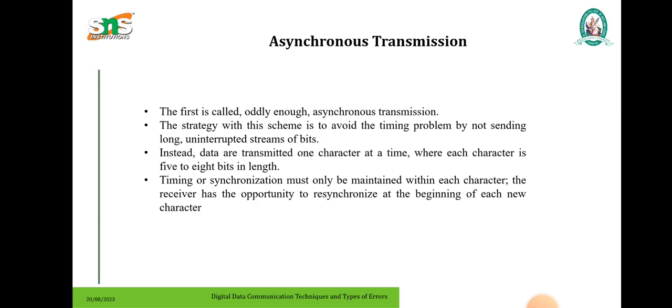So timing or synchronization must only be maintained within each character. The receiver has the opportunity to resynchronize at the beginning of each new character, so if there is any long data, it can be divided into small segments and then sent.